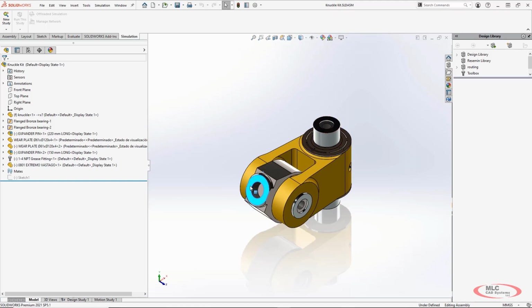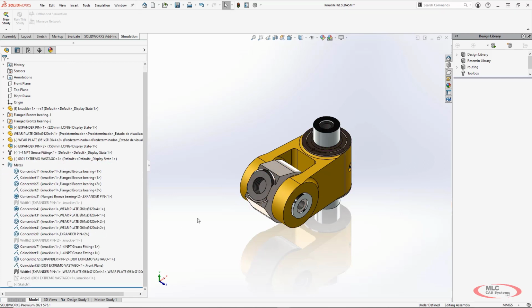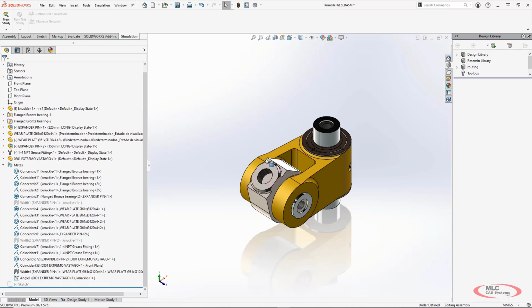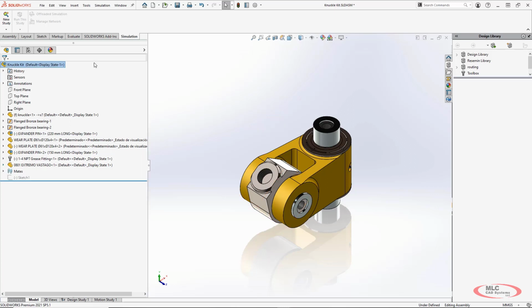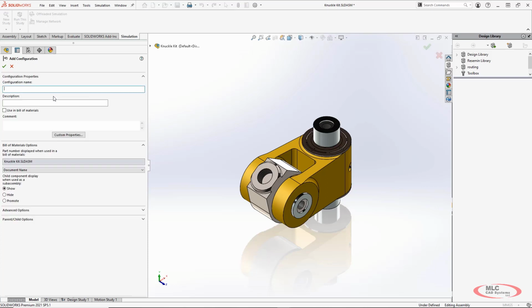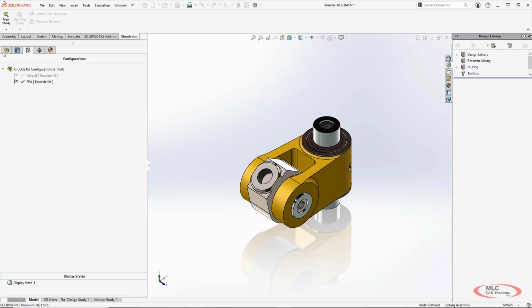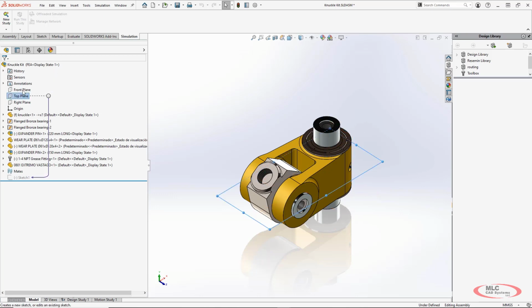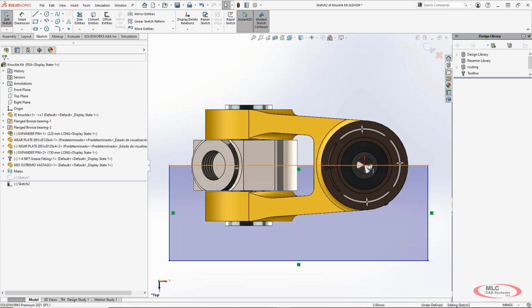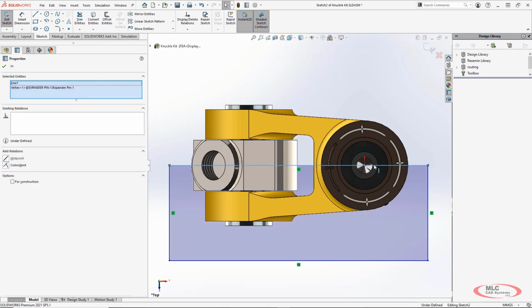There are a few things we want to set up. Right now this isn't fixed, so for this study, I'm going to say this is going to be a 35-degree angle. I have set up an angle mate from before that I'm just going to unsuppress. Then I'll create the symmetry. For this, I'm going to add a FEA configuration, finite element analysis, and then use your typical SOLIDWORKS CAD to start this geometry. I'll make sure that this is in the center.